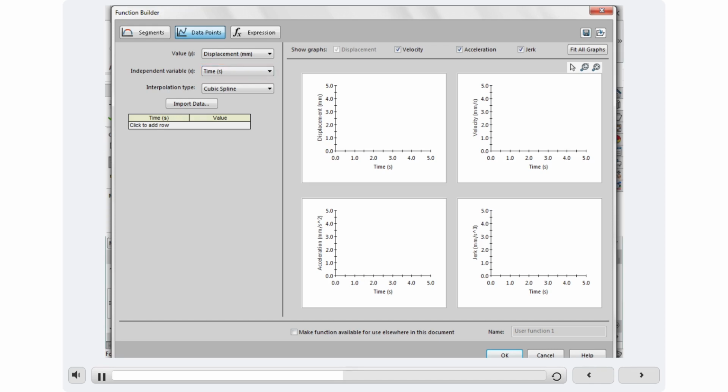In order to calculate the displacement between the data points, an interpolation method must be used. There are 3 interpolation options available: linear, cubic spline, and Akima spline. A linear interpolation will draw a straight line between the data points, while a spline will create a curvature continuous path through the data points. Generally speaking, a cubic spline will over-exaggerate the curve through the data points. Therefore, we will use the Akima spline interpolation. Click Akima spline for interpolation type.